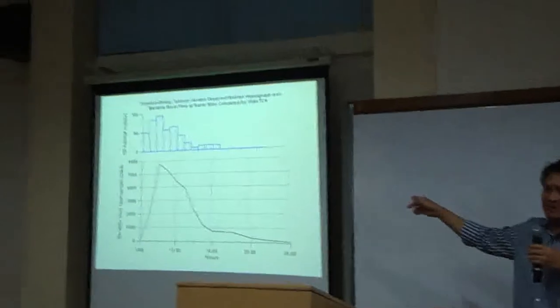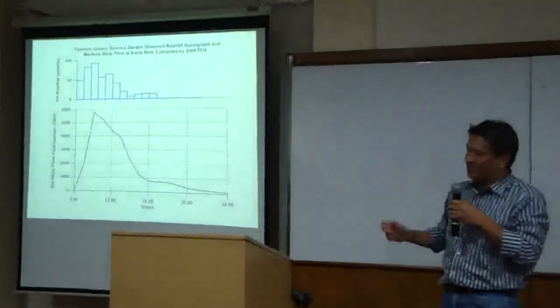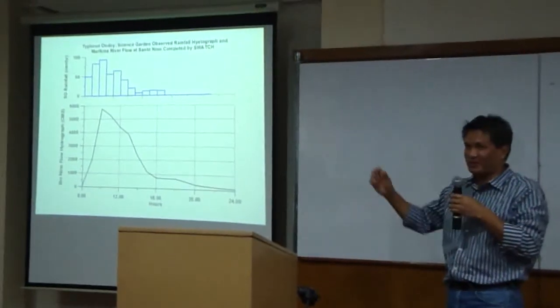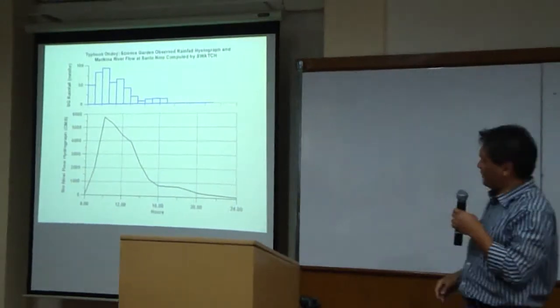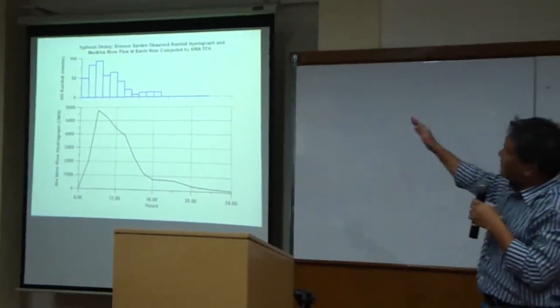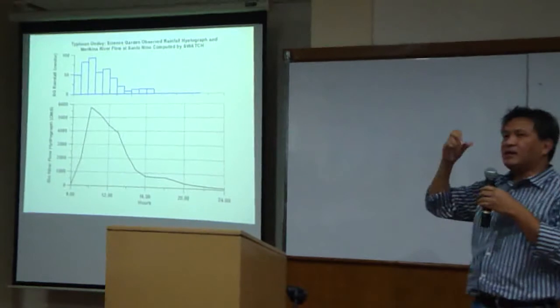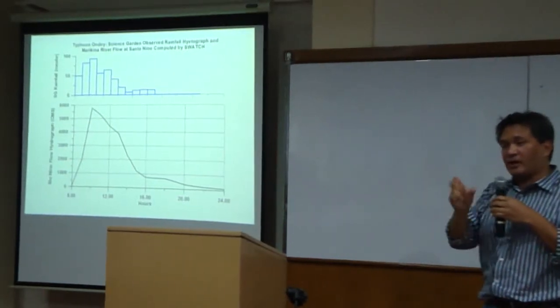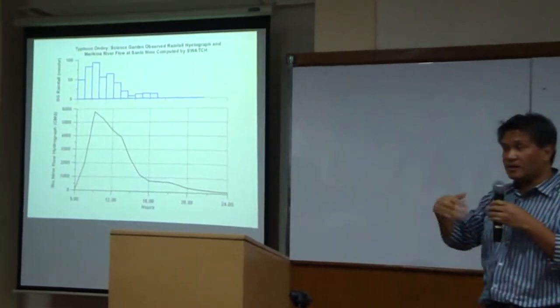She gave me 3-hourly data. Finally, at around 6 last night, I was able to get the hourly data from a friend in Gaza. So given that, that's the only rainfall data that's available on an hourly basis. Then Professor Johnson mentioned the area reduction factor, which we applied as 0.6. So given that, we then put it in the watershed model.